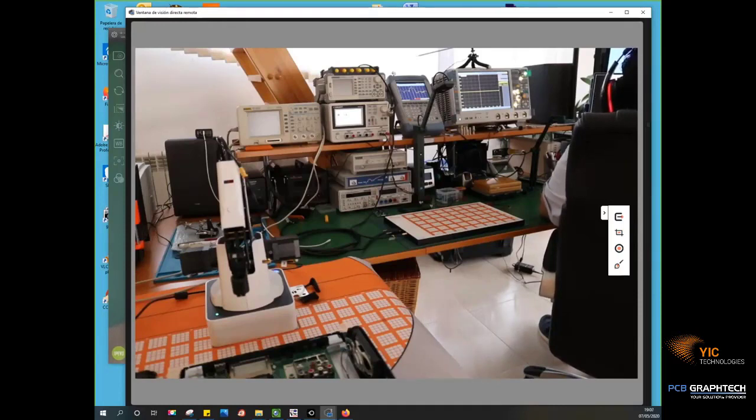Well, this is the first slide to introduce the idea. We are worried about EMI. What is EMI or EMC? It's a problem for many electronic manufacturers. The idea is that some kind of transmitter of electromagnetic energy sends the signal to some kind of victim. Usually, the victims are circuits working with very small voltages, currents, or in general signals. That is because typically a good EMI receiver is a radio or a TV receiver. But really any kind of electronic product can fail with electromagnetic energy.